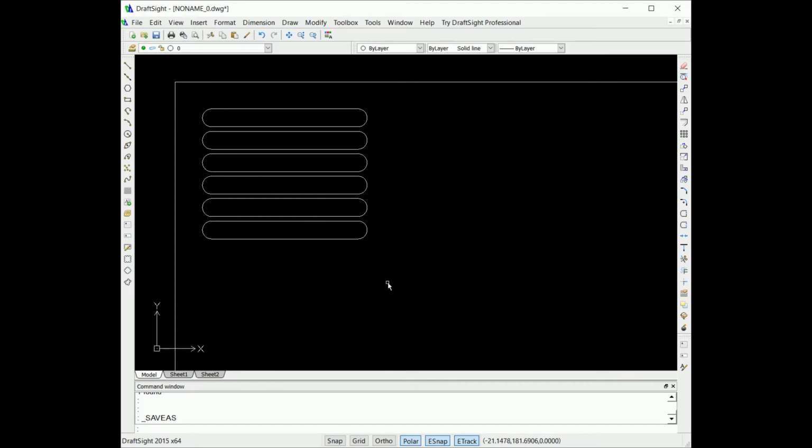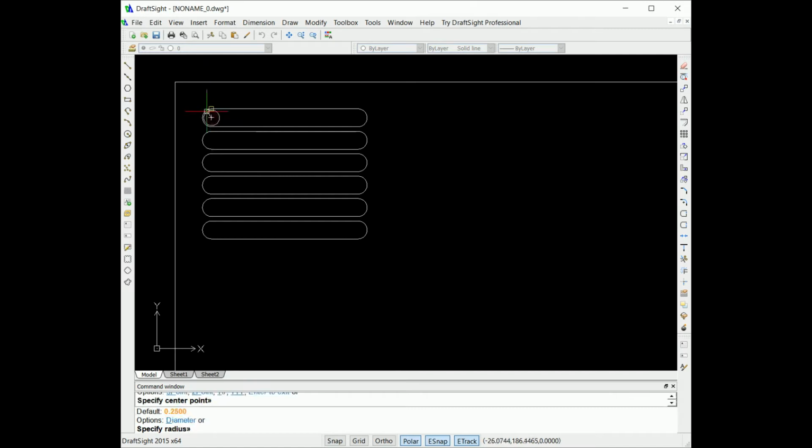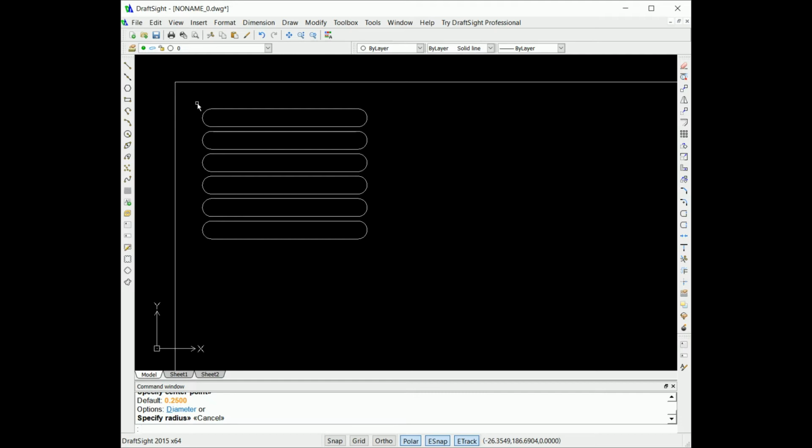This is a pretty simple drawing, and just for your benefit, I'll go ahead and add the 4 mounting holes. And don't forget, we can do our relative positioning. I'm going to select the center point of this hole for my circle and then hit escape. And now where I want my hole is out here. So I'm going to hit enter again for repeating the circle command.